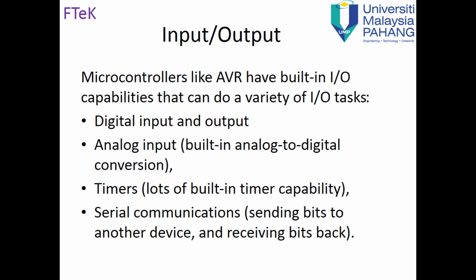To understand input-output, we should know that microcontrollers, and AVR is one of them, have many built-in capabilities that can do a variety of input-output tasks. The list includes digital input-output, analog input, which is usually connected to an ADC, analog to digital converter. Timers can be considered input-output devices, and we have serial communication, which is used to send and receive bits from other devices bit by bit serially.